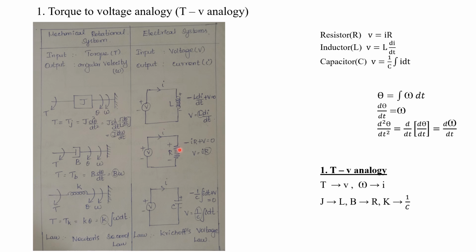Only when we draw this resistance here, we will get the similar equations. So here for this resistor R, we have to give an input voltage V. Due to that there will be a current I that is passing through the resistor R. Now we can apply this in a closed loop, isn't it? Now we can apply Kirchhoff's voltage law. So we have to start from here. Along the direction of current flow, we have to put plus minus. If you are starting from here and going through the circuit like this, from plus to minus, it will be considered as minus.